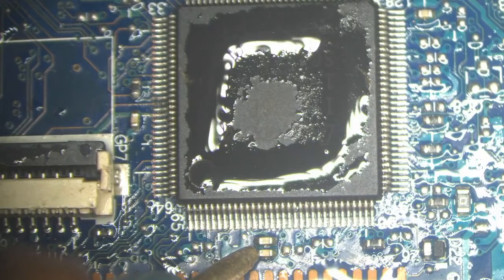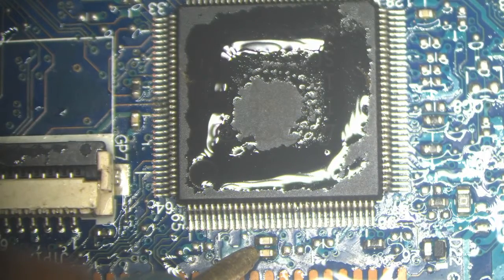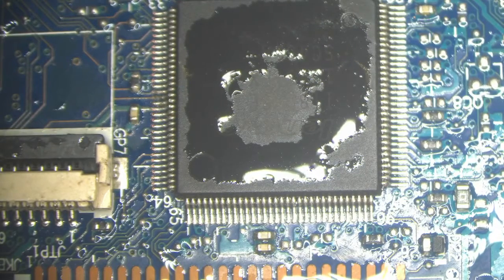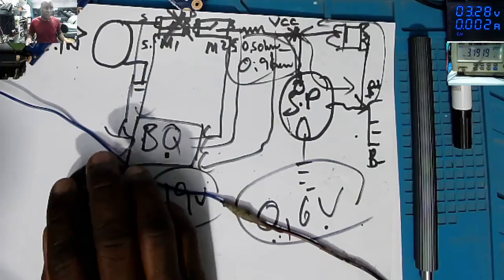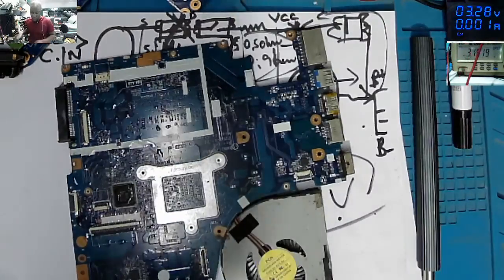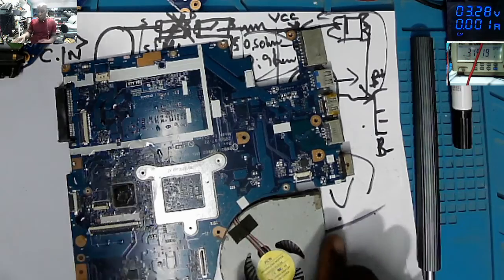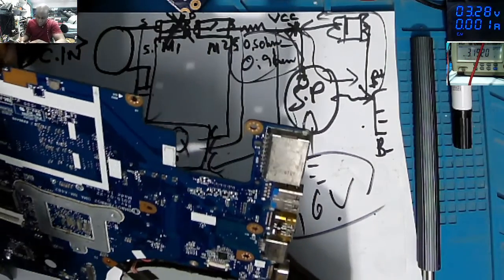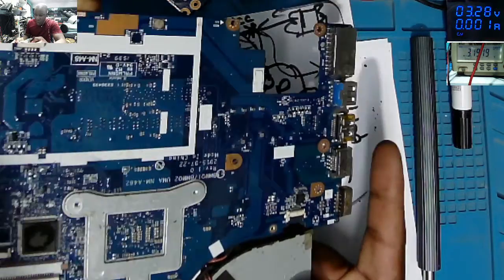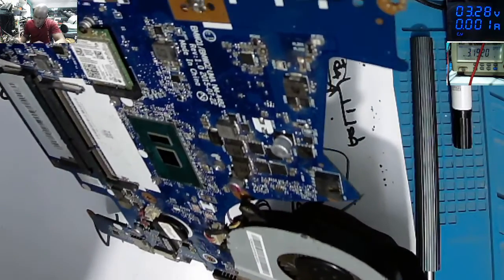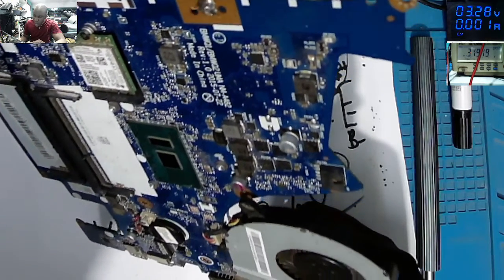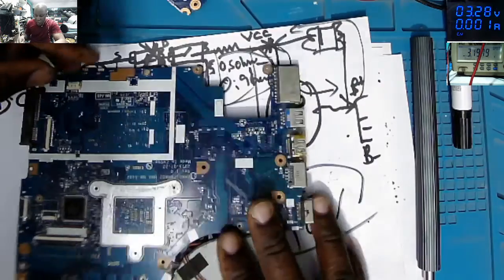So what we know by now: the EC chip is dead, and the main 19 volts is shorted.